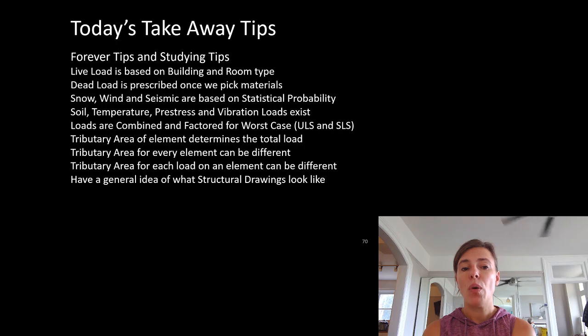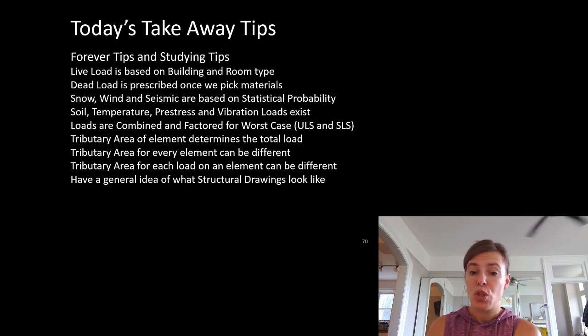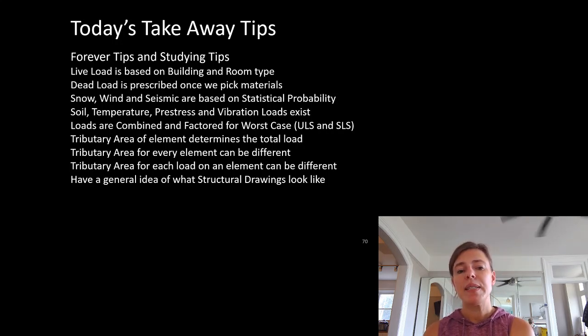That we have loads with combinations and importance factors and how to calculate those. That tributary area determines the total load on our object. That it can be different for different objects, and it can be even different for different loads on an object. And you should have a general idea of what structural drawings look like. So there's a lot to take away here.